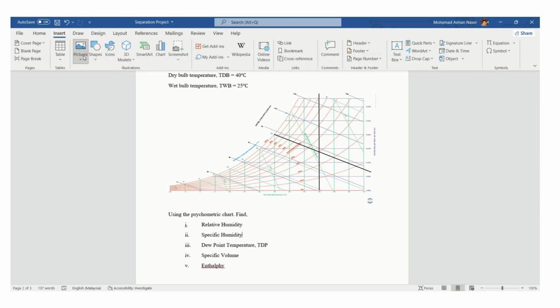So I take the line. Relative humidity. Here there is a line of relative humidity. So 0, 10, 20, 30, 40, 50, 60, 70, 90 and 100. Now here is the intersection. So the intersection shows that the point is at the relative humidity 30%.